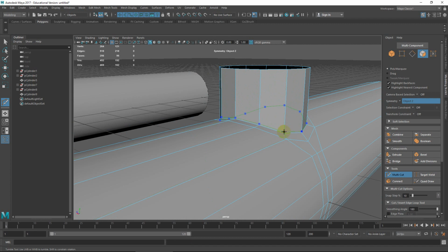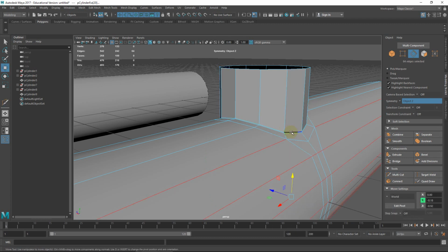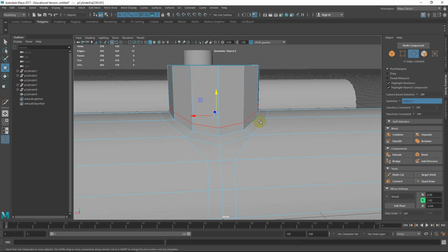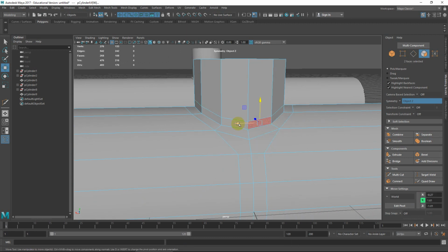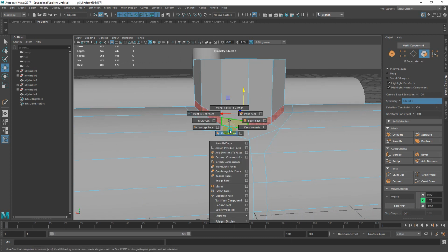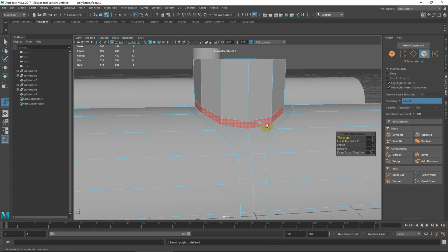If you want to be fairly good at mimicking that shape, I want to create that lip like I did in the other mesh, but I actually want to do it via an extrusion here. So I'm going to get very, very close, as close as I can. Click to set that loop, and then go back to edge mode. Double click this. I don't need slide in this case because I can just pull up along the axis because I've kept things nice and neat. Let's go across the face here and do maybe an extrusion on local Z.